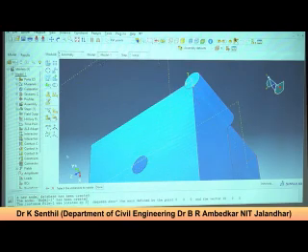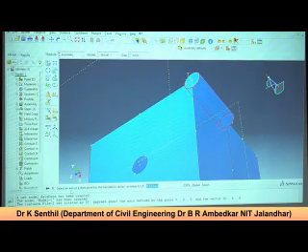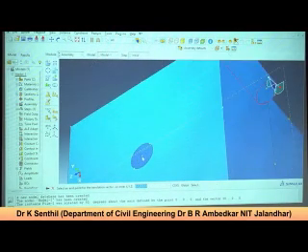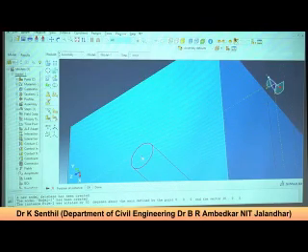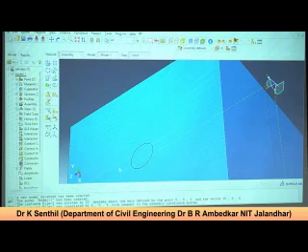Now you go to translate, click this, done. Now it is asking for the starting point, from which point to which point you have to move. So the starting point is the center of this pile, and the end point is this one. Yes. Now the pile is inserted.